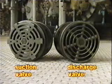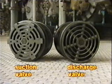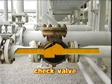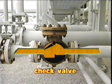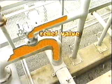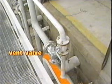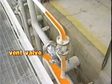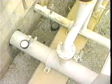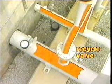In addition to the suction and discharge valves, there are a lot of other types of valves in the inlet and outlet piping of a compressor. Check valves ensure that gas flows in one direction only. Relief valves prevent overpressuring of the compressor and piping. Vent valves allow depressuring of a single compressor cylinder or the complete compressor package. And recycle valves allow the same gas to flow through the unit a second time.